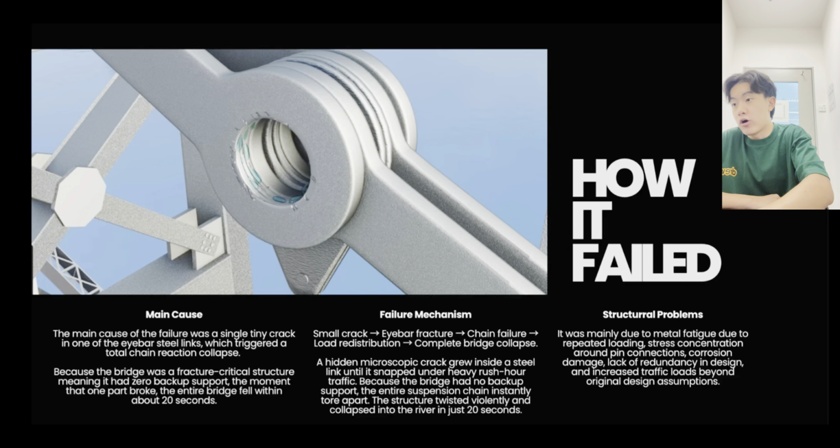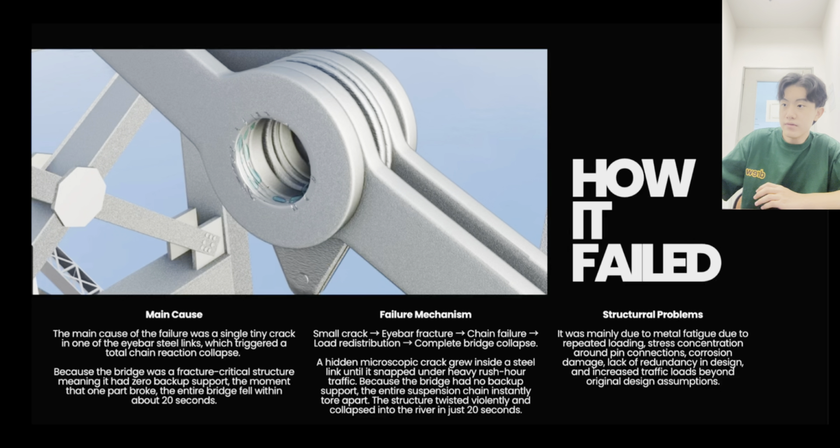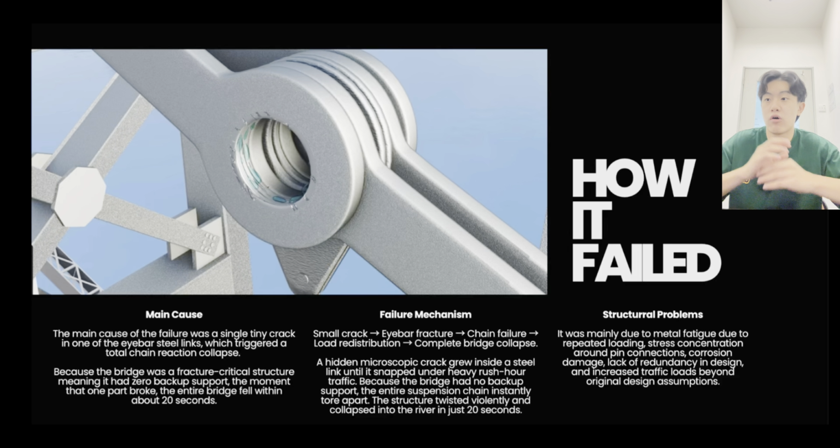So moving on, there are several factors which contribute to the growth of this crack. The first factor was stress concentration around the pinhole connections. As explained earlier, the I-bars contain holes for the connecting pins. These holes created areas where stress became very concentrated. It is all focused at that one point, making them the most vulnerable locations for cracks to form.